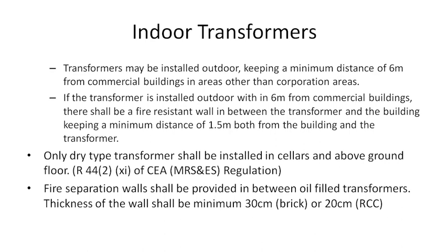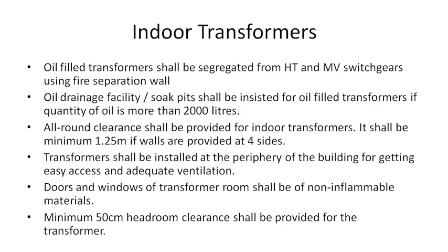And a fire separation wall has to be provided between oil filled transformers. Thickness of the wall shall be minimum 30 cm for brick and 20 cm for reinforced cement concrete.